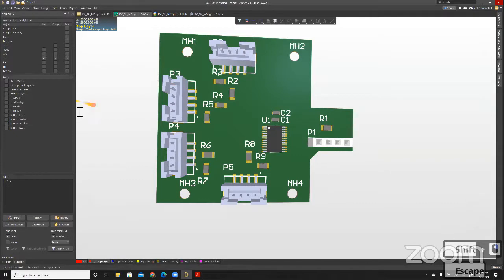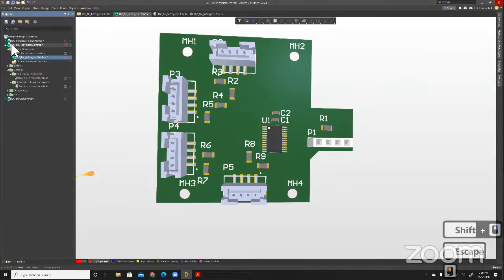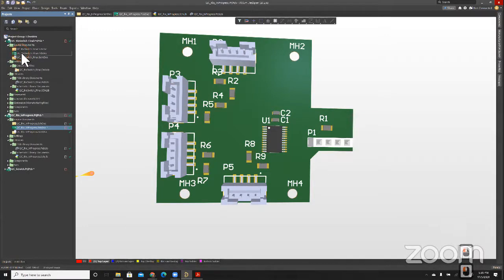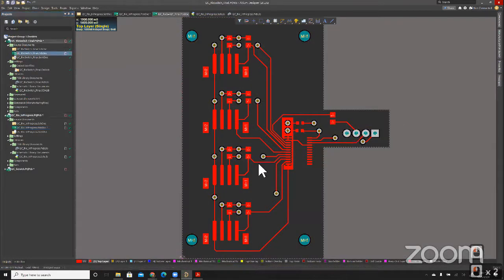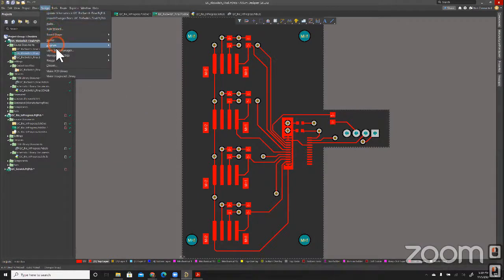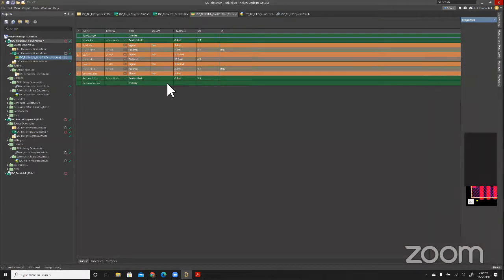And so I'm actually going to kind of jump ahead again to the final project that I did earlier today to show some of the different things. Yeah. So I've got about 10 minutes left. There's a lot of things that I'm kind of skipping. There's under the Design Layer Stack Manager, this is where you would go add additional layers. For most FRC stuff, you can get by with just 2 layers.